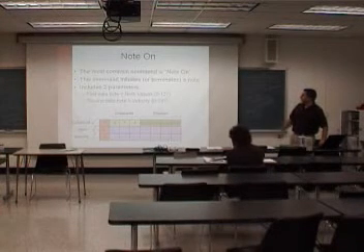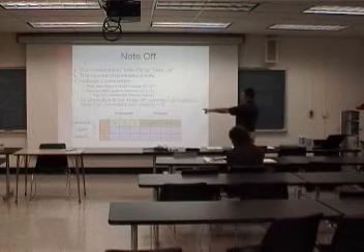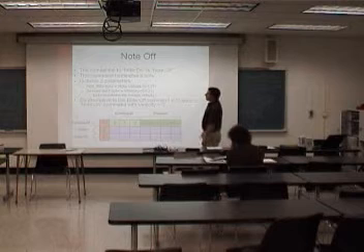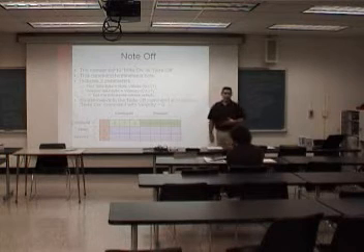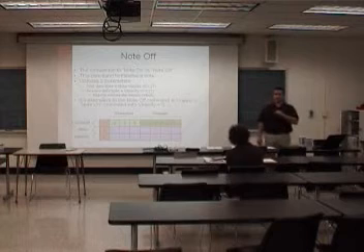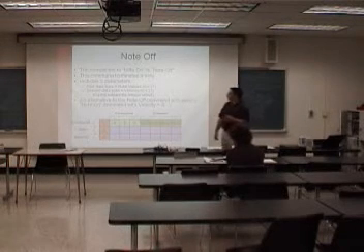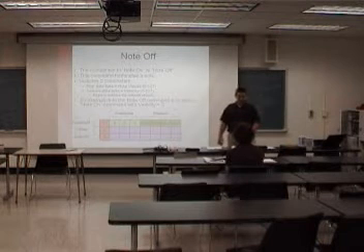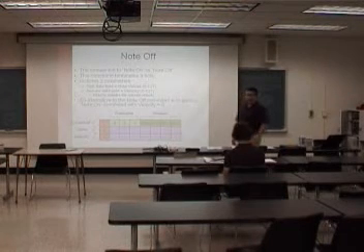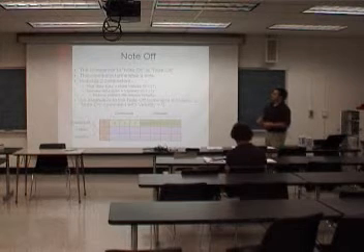The companion command to note on is note off. Okay, so this is command 000, and this terminates the note. So pretty much any time you play, there should be a note on command when you press the key and a note off command when you release it. And we'll try to see if we can see that. I downloaded the MIDI analyzer, which should be able to read live MIDI streams.